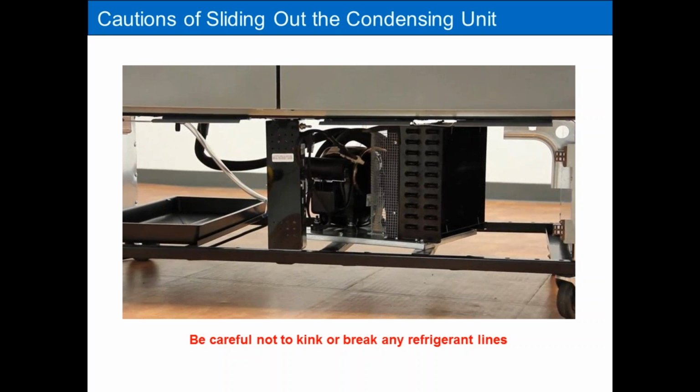Recently, I was working on a beer cooler where the same scenario happened to me, but I didn't realize the problem until actually 2 days after the fact. I had pulled out a condensing unit for a beer cooler just to change the condenser fan motor. So it was a simple fix. Pulled out the unit, changed the condenser fan motor, pushed it back in. It was in a bar, pretty loud, pretty crowded. I didn't hear the magic hiss, but apparently when I pushed the unit back into the beer cooler, the suction line gave free, and all the refrigerant dumped out. I didn't realize it at the time. I pushed it back in, took off.